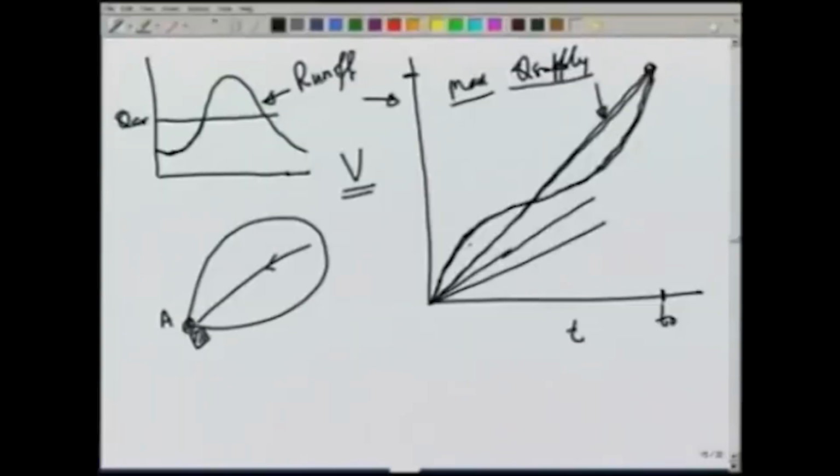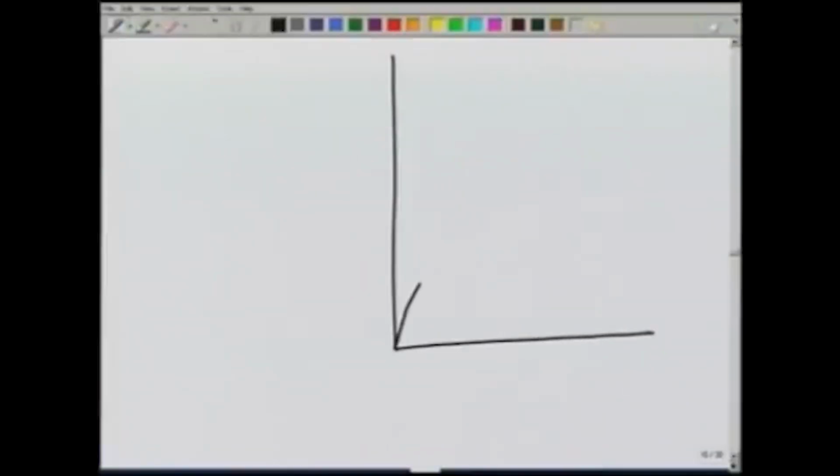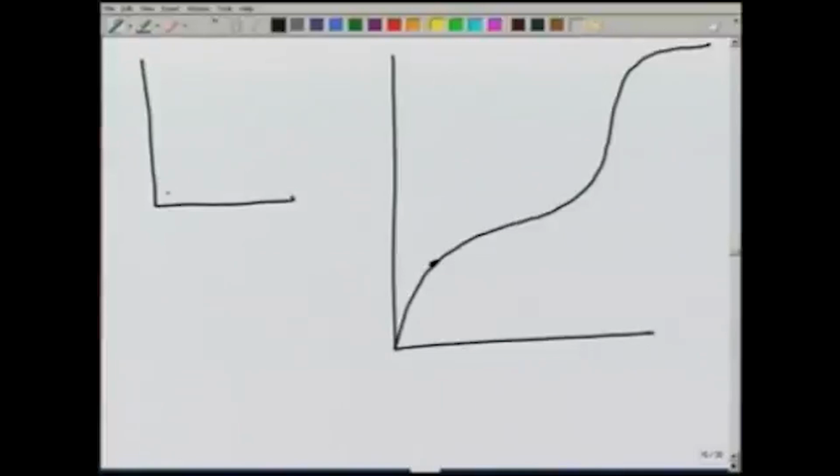So, we can always supply anything at a smaller slope, but more than that we will not unless we take water from somewhere else. So, let us say that we want to supply this maximum rate by creating some storage facility here. The question to be answered is, what should be the capacity of that storage structure. So, from this figure we can see, if we draw the mass curve again like this, the idea is that during period of low flows we will take water from the storage, and during period of high flows we will divert the additional water from the stream to the storage.